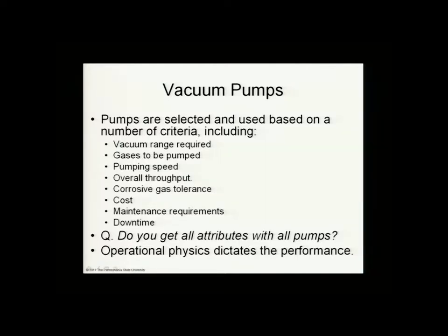And then how fast do we want to be able to move samples in and out of the chamber? How fast can the chamber be pumped down after a sample is completed? This has to do with the ever-present engineering issue of cost and how many products can you make in a unit time. You can't be spending a lot of time pumping systems down, and so that's an overall issue.